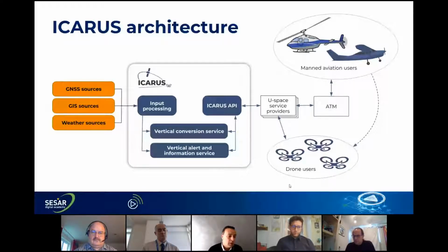And finally, we need one unique certified barometric pressure service provider, because this information is useful to calculate dynamically the offset between the WGS84 datum, which is a geometric information, and the barometric information that, of course, is variable considering the day. Next slide, please.